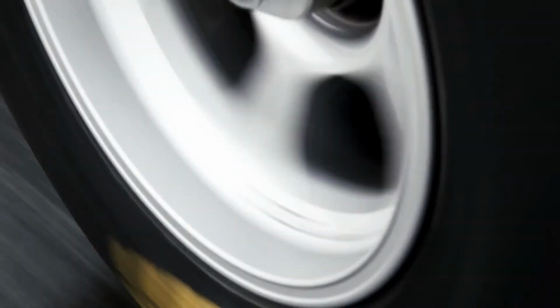conditions such as the weather, the state of the tyres, the consistent behaviour of the driver, they're things that are changing, however subtly, all the time. So track testing is the most realistic way of testing, but it's also the least repeatable because of these changing conditions. And track testing also wears out the powertrain, wears out the tyres, and so costs much more than other research methods. Model testing costs less.